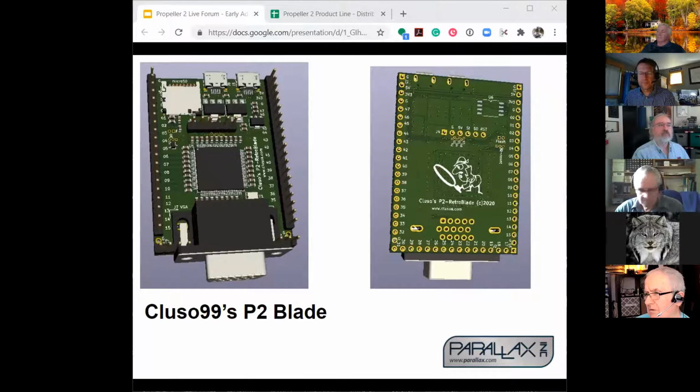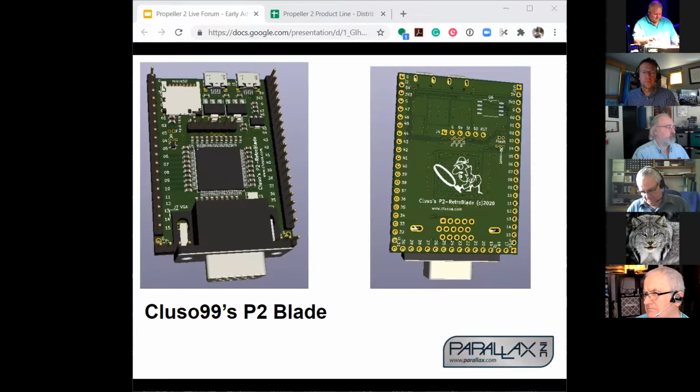So what I'm saying is create a pin group. If you're writing out the sine information to the pin group, then disabling them with the DIR set would work. When you re-enable them, your code would be continuing to output and they would all be in phase with each other.